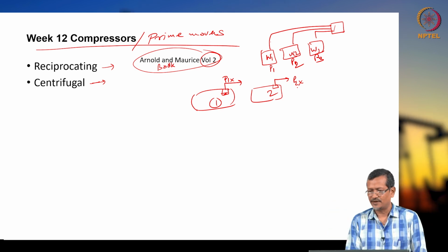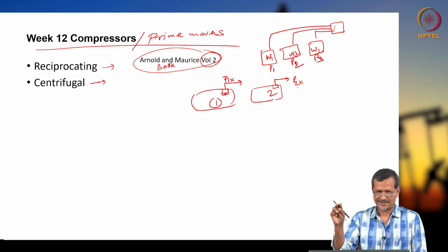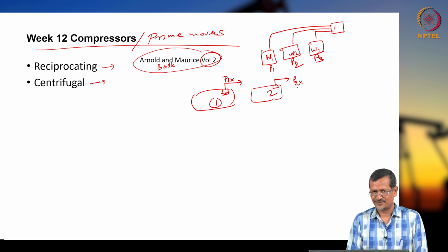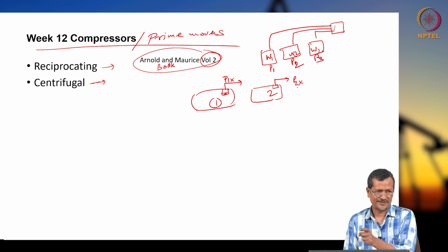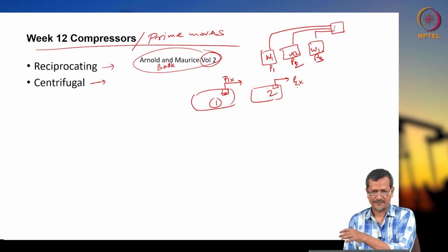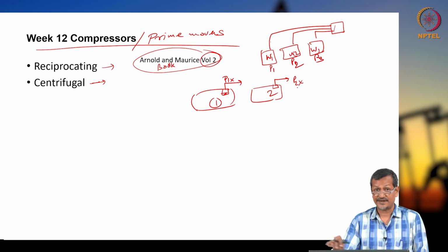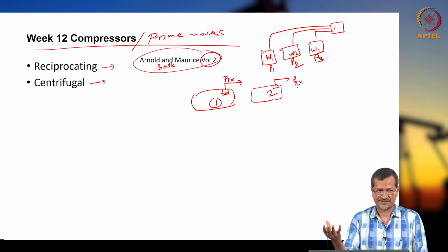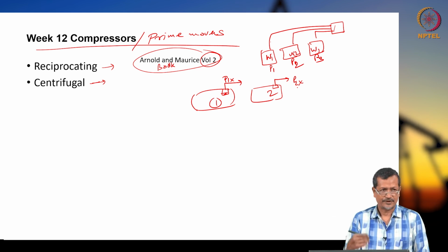You cannot connect them directly, otherwise high pressure gas will enter your low pressure separator. So you must manage that using some compression system. Separator 2 may require compression or more pressure, so you have to handle the system that way.